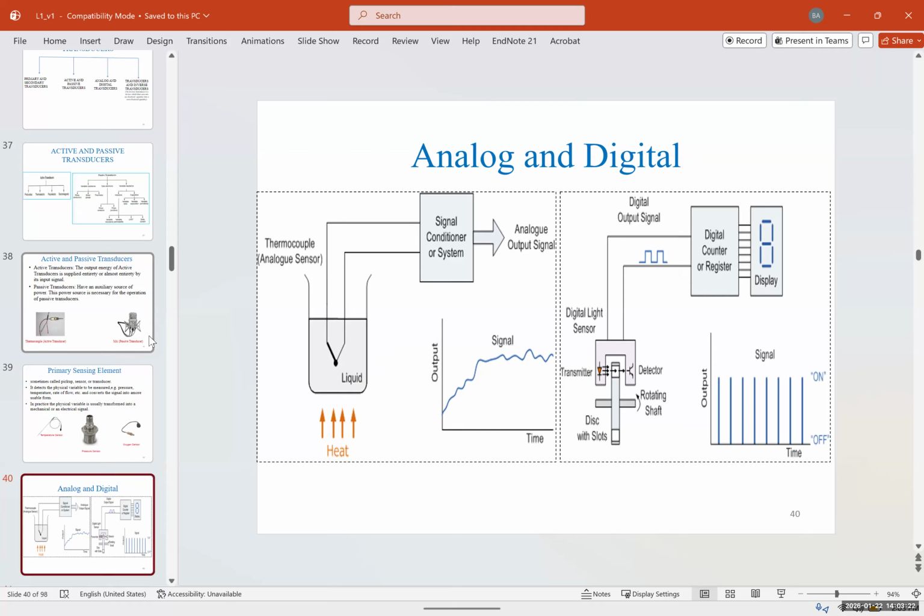That's the reason a microcontroller like the Arduino usually has just one or two analog inputs maximum and 20 digital inputs. The same thing is true for microprocessors. Some of them don't even have an analog input. So before you even feed that to a microprocessor, it must be converted to digital.